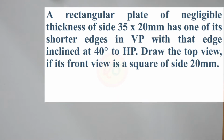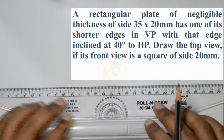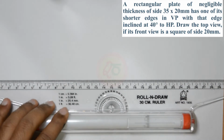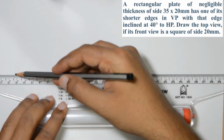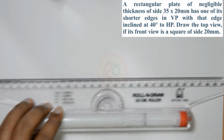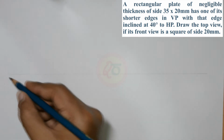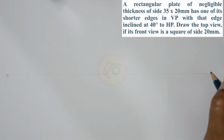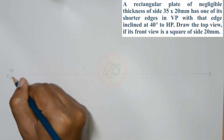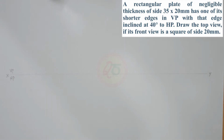So, we'll first draw the XY line. I generally prefer drawing it for the entire length, with an HB pencil. Name the ends as well as the projection planes, which are VP and HP, the vertical plane being above the XY line and the horizontal plane being below the XY line, since we are dealing with first angle of projections.